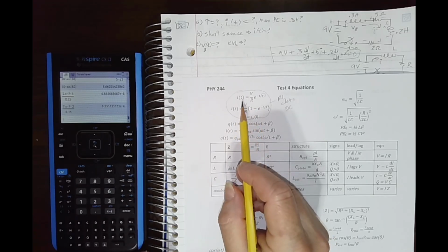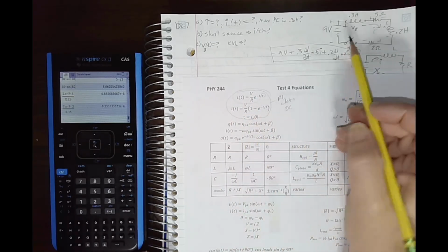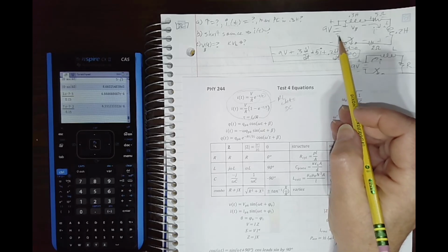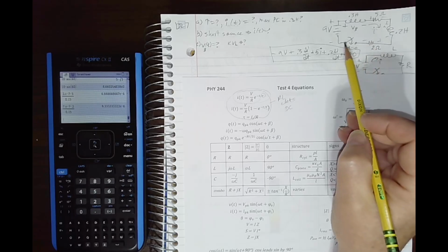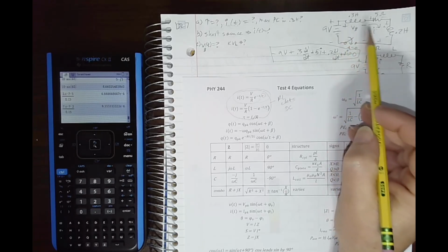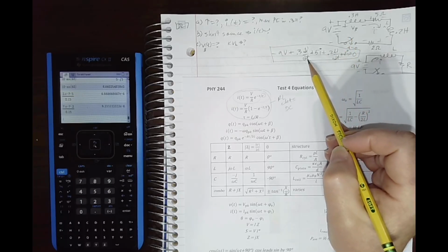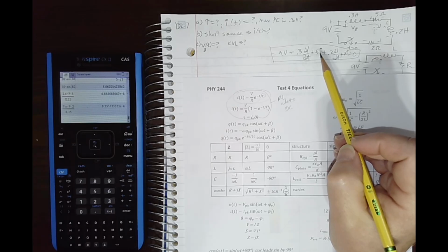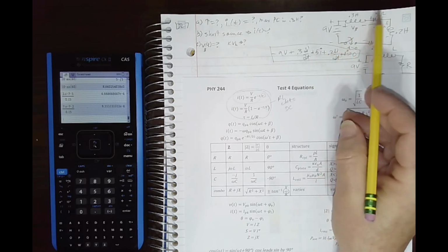It depends on what the circuit is. So if we see this first one, what's going to happen in this circuit? What happens with inductors? At first, when you close the switch, we're going to have current flowing, but these are basically coils. Remember, coils don't like change, and so they don't like changing current, so it's going to slowly ramp up the current.